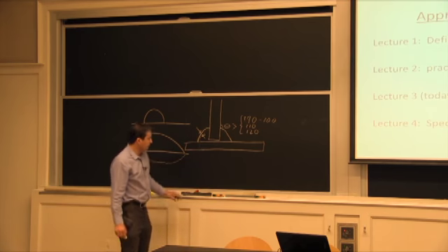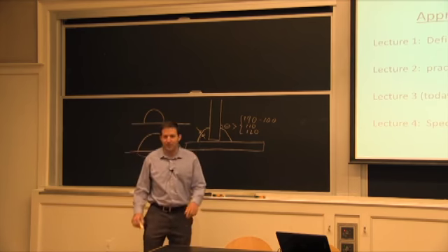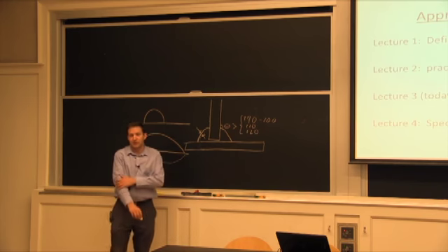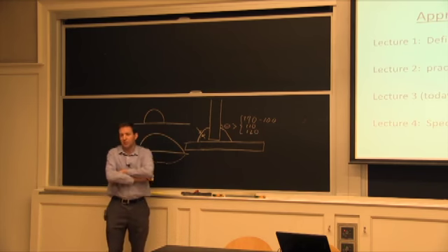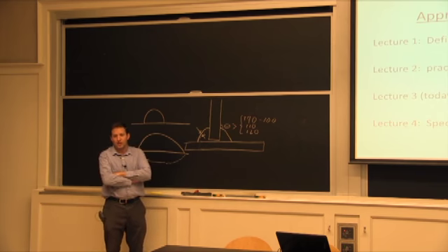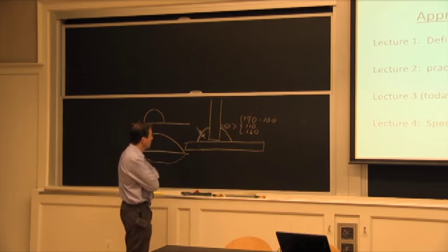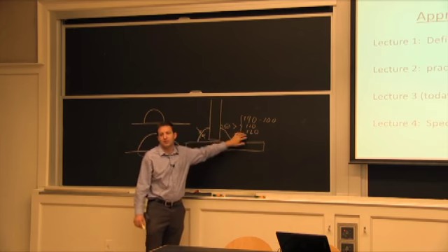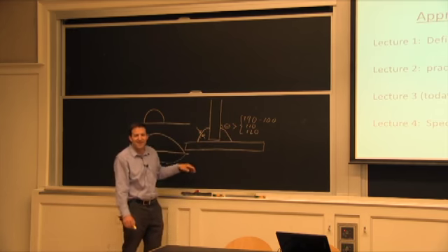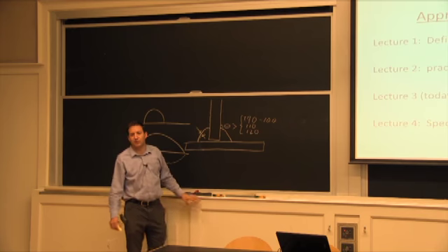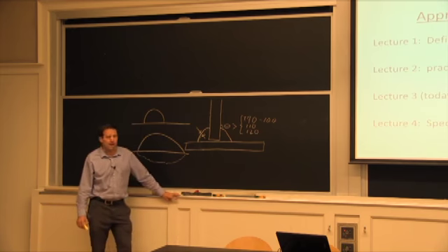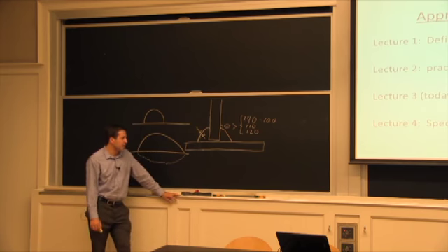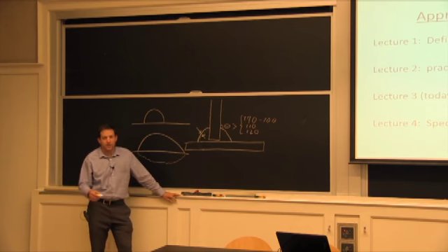And from my perspective, this is even harder to evaluate, how much convexity you've got by looking at it visually. But if you hire an inspector, say, come and look at my welds, these are to be shipped to Europe for this construction project. Well, the inspector should be informed as to whether he's going to inspect this way or this way. And maybe he's trained to do only one of them by experience. So inspection also ties into our factor of safety.